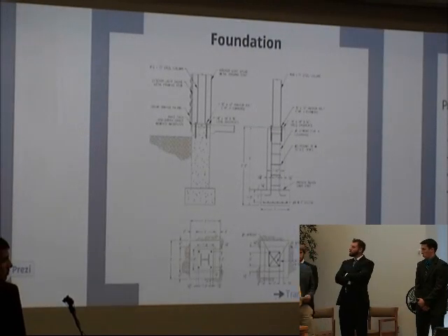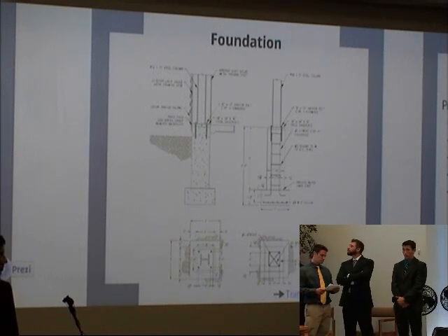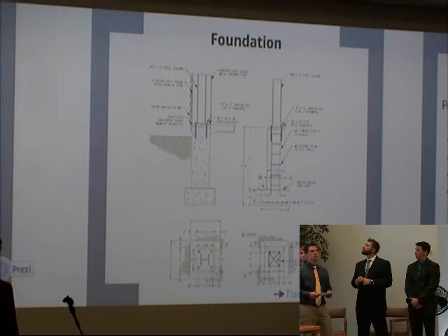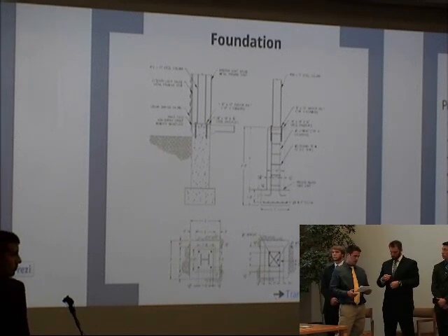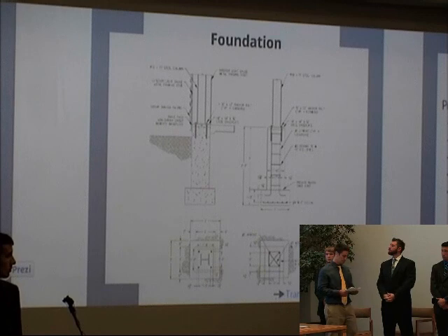Hello, my name is Rob Mandalara, and I'm part of the geotechnical team. After the site investigation, the geotechnical team analyzed the soil properties. We determined the existing soil properties were good and that they were suitable for shallow foundations. Neither deep foundations nor ground improvement is necessary for the site.